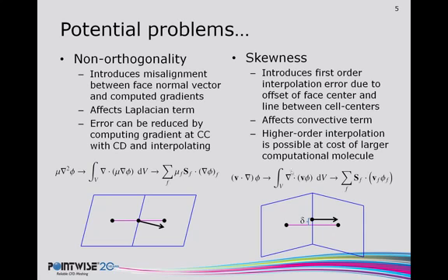In the presence of a vertical gradient here and a horizontal velocity field, the value that is going to be advected across this face is going to be misrepresented whenever you use the cell-centered values, because the value at the face is inherently different than the value here as computed through the interpolation of those cell centers.